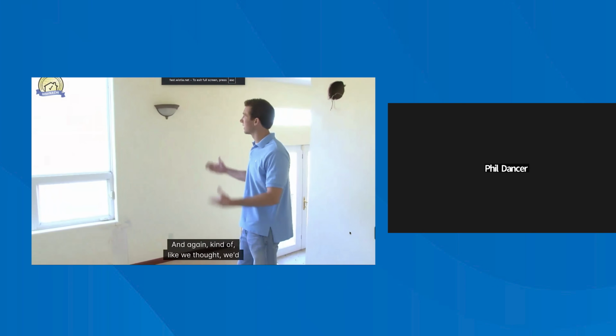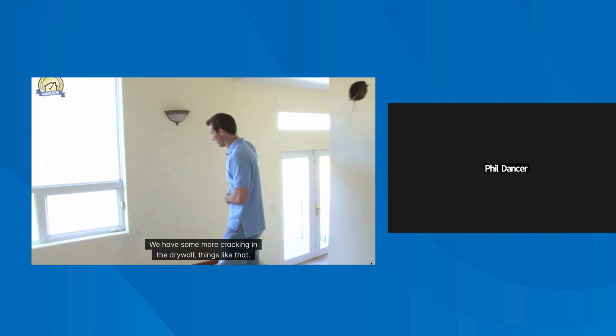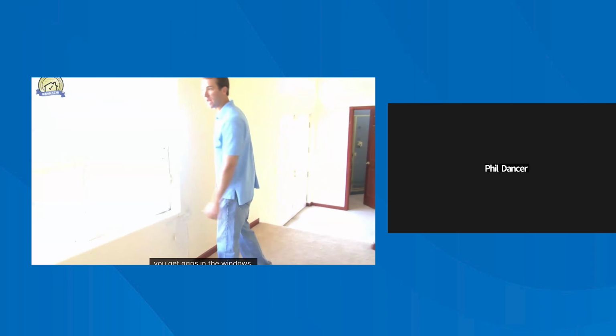And again, kind of like we thought we'd see movement over here, we have some more cracking in the drywall, things like that. This one, we're actually seeing some cracking through underneath this window to the point where we're getting some water intrusion. And a lot of times what you see with this vertical foundation movement is some separation in the window, and you get gaps in the windows.